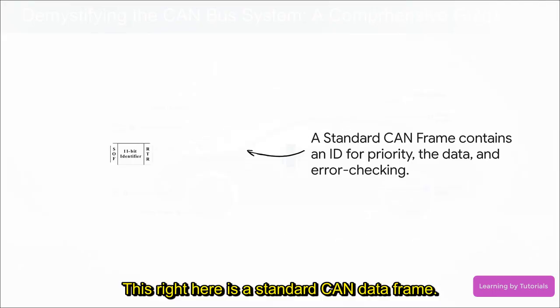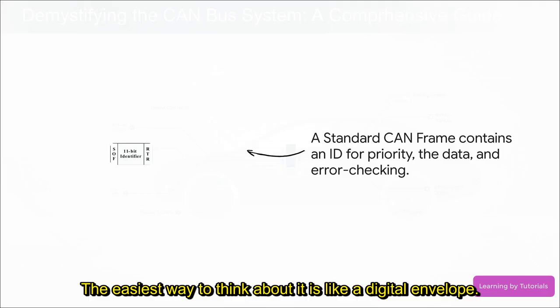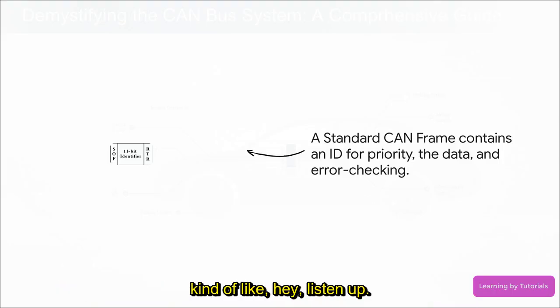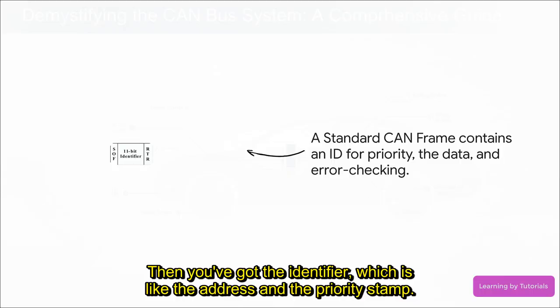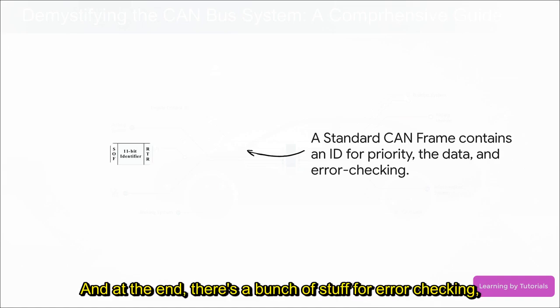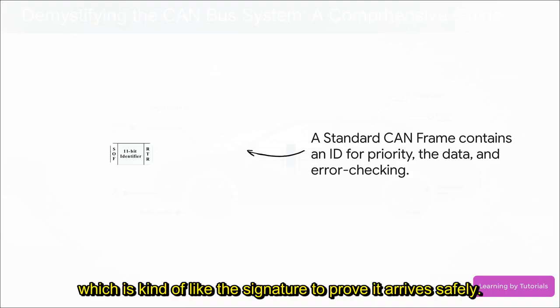This right here is a standard CAN data frame. The easiest way to think about it is like a digital envelope. It's got a start signal at the beginning to get everyone's attention, kind of like a, "Hey, listen up." Then you've got the identifier, which is like the address and the priority stamp. Then comes the actual data, the letter inside the envelope. And at the end, there's a bunch of stuff for error checking, which is kind of like the signature to prove it arrived safely.